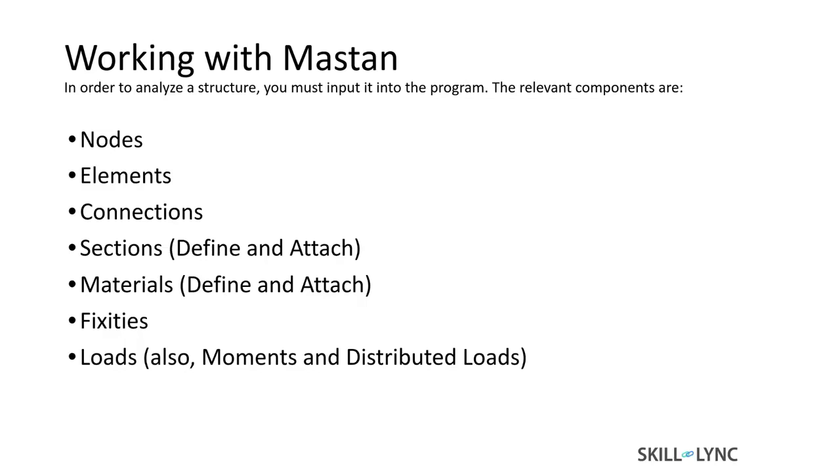So as I said in my previous slide, working with Mastan, you need all these concepts, starting with nodes through to the loads. And one thing to keep in mind when you warm up or surf through Mastan is that it's a unitless software. So if you input your load in kilonewton and your frame is in meters, and you expect your load value or the boundary conditions or the moments to be in Newton millimeter, you won't get that. So be consistent: use kilonewton meter, Newton millimeter, or Newton per mm square.